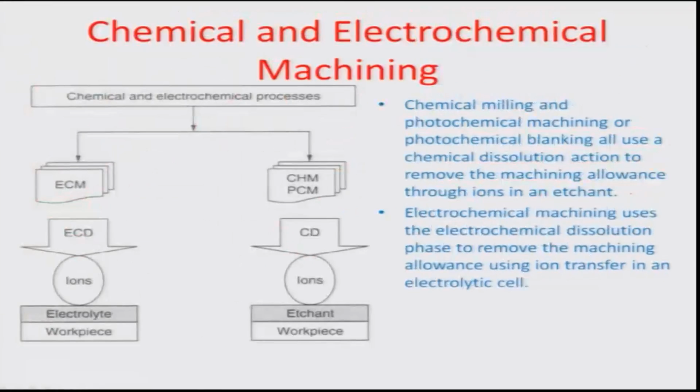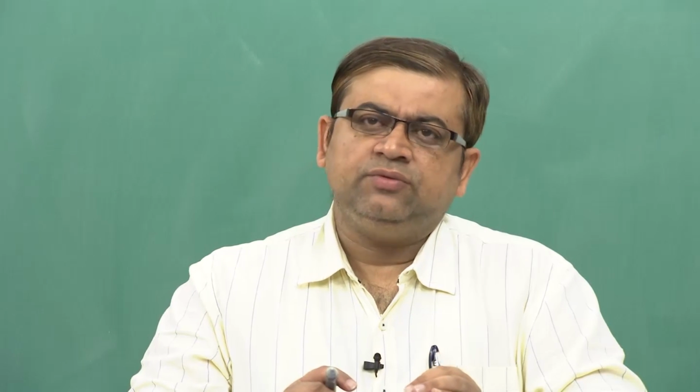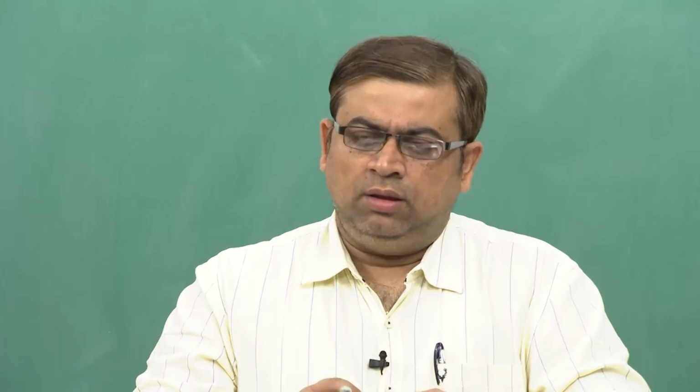So, we have a similar kind of an alternate machining using chemical and electrochemical route. Okay. So, we talk about in this case, for example, the chemical machining process, you have some kind of an etching or an engraving action. So, there is an acid which interacts with the surface of a workpiece, and because of this interaction in a very selective manner in some selected zones, there is a local erosion of the workpiece material which results in the formation of an etch zone or an etch area. So, there is literally a dissolution of the material into the medium that is sent in, because of which there is machining taking place. So, we call that chemical machining.